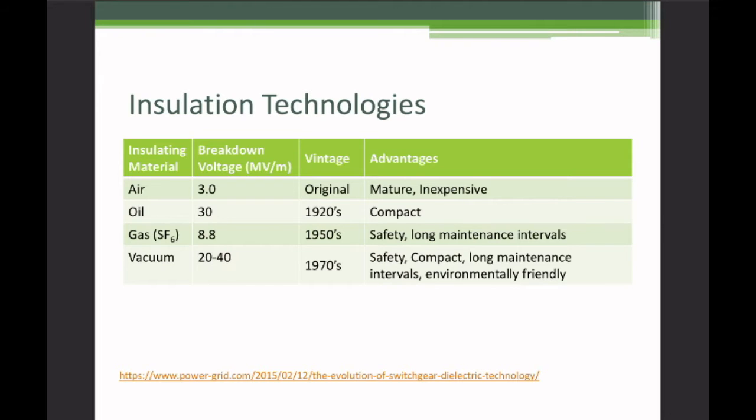And so if you find a fused cutout that's 30 or 40 or 50 years old and the fuse is operated, you'll be able to put in the same fuse that's riding on your truck. If the fuse holder's blown, there's a good chance the fuse holder in your truck still fits. And so that continuity really helps, and the low cost really helps. And so as a result of that, you still see this stuff everywhere.